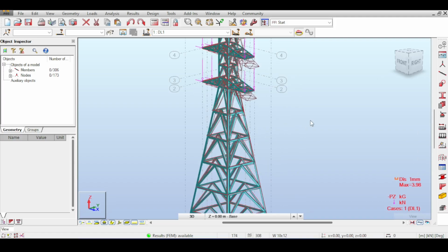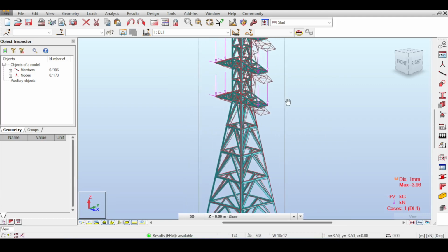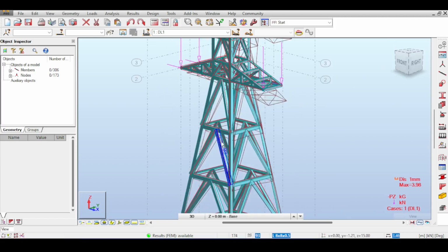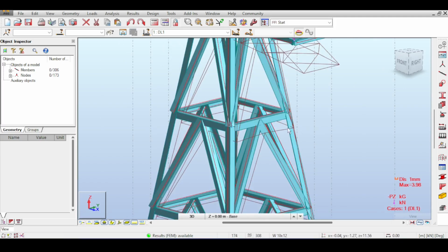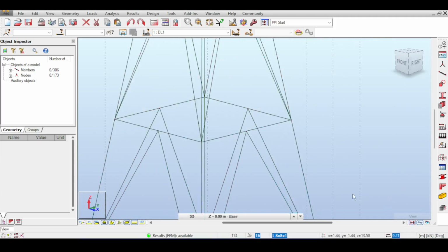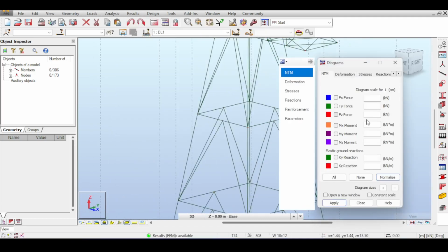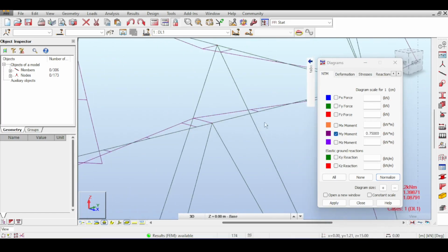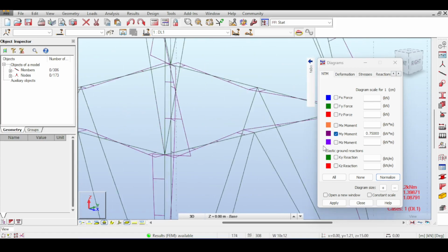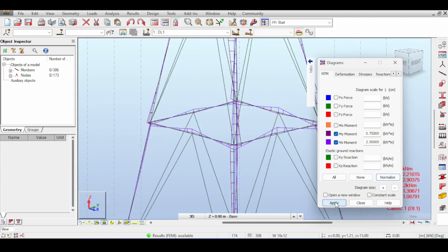Okay, so there was one little discussion with our dear subscriber, Donald Khani. He mentioned rightly so that I have forgotten to release those things, and he's right. To prove his point, I will show you the bending moment diagram very quickly. If you go to diagrams for bars and y, you can see that those elements do have moments around the y and z and all kinds of axes, which means that those were not released.